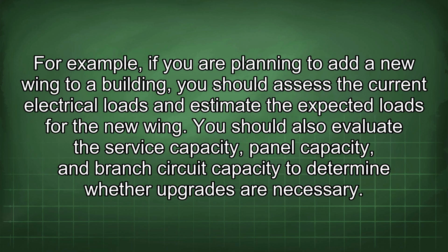For example, if you are planning to add a new wing to a building, you should assess the current electrical loads and estimate the expected loads for the new wing. You should also evaluate the service capacity, panel capacity, and branch circuit capacity to determine whether upgrades are necessary.